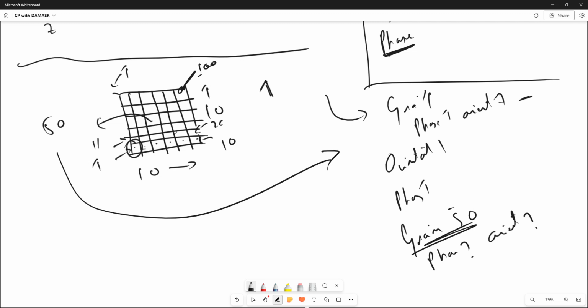Do you understand that? Yes. One question. First, for that, now we have one material and we define this material. Now for this, for example, I go to part 50 or phase 50. Is it needed to define 100 grains material or not? It's not needed. For example, based on the material, DAMASK finds this and allocates these properties to, for example, phase 50. Or no, we have 100 parts, we have to go step by step, grain 1, grain 2, define all of them.